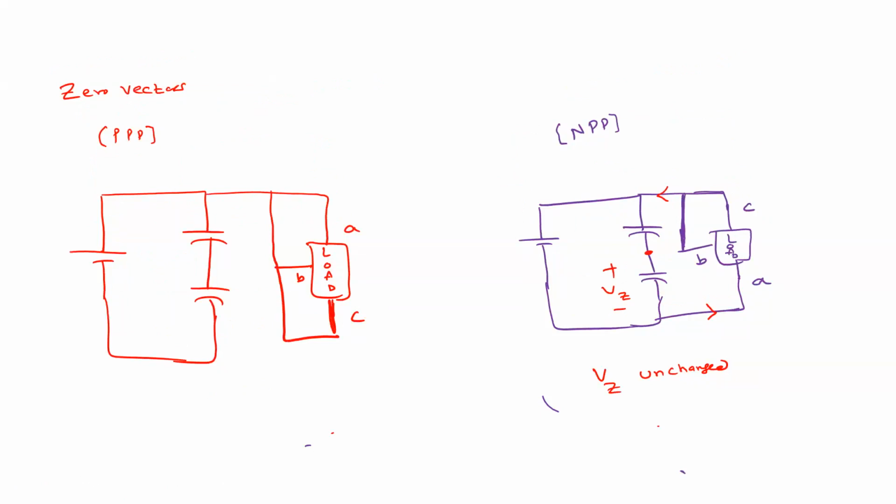Okay. So what is the meaning of this? That means A phase, B phase, C phase are short circuited, right? Understood? All three phases are connected. So that is providing a closed loop for the load circuit, and it is not delivering any current from the source. So there is no current flowing here from this source. Right. So now will it affect the neutral point voltage? Will it affect the neutral point voltage here?